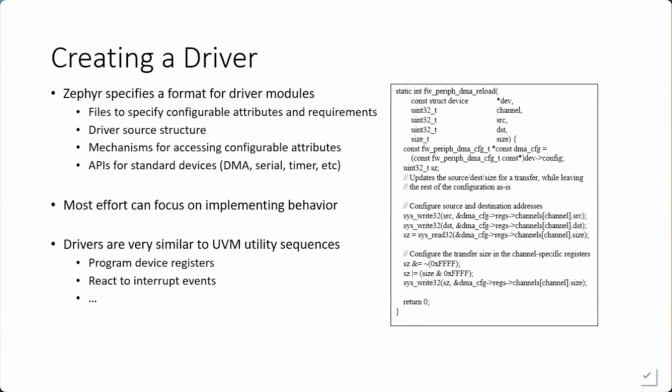Now, I think the significant thing to look at from a task of driver creation here is that the operations that we're performing here, writing registers, reading registers, having behavior that's triggered when an interrupt fires to manage the device, these are all things that as UVM sequence writers we're very familiar with. It's the same task to write in SystemVerilog using the UVM register model.